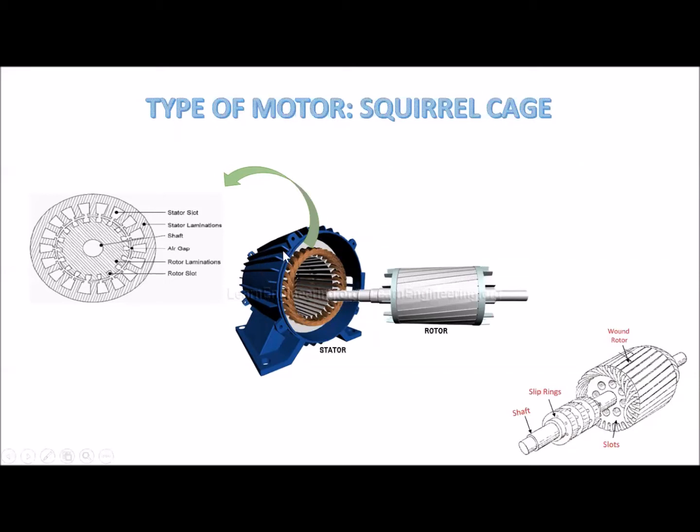The stator over here is responsible for generating a rotating magnetic field in the induction motor from a three-phase alternating current. As you can see over here, this is the stator lamination. The stator laminations reduce the losses, which are eddy current and hysteresis losses, that occur during operation. For the rotor, it has a series of rotor slots. The rotor slots are composed of punched laminations stacked together and provide a space for the rotor winding.